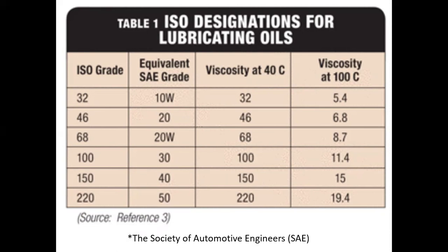And at 100 degrees Celsius, this viscosity lowers down to 19.4. So, as we've discussed from our previous discussion, please take note that as we increase the temperature, the viscosity of our fuel or lube oil actually decreases. So we can see here the trend.